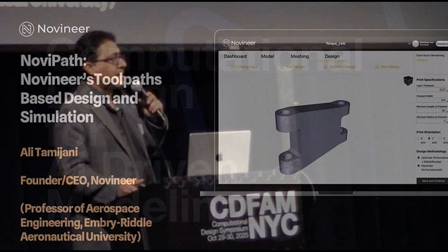So this is a short demo of how it works. You take a picture, provide that picture, and it creates STL and STP. Then you can go to the next module, apply loads and boundary conditions, and it optimizes the geometry. Then you go to the next module, provide material properties, and it optimizes the manufacturing toolpath. Here are some additional examples, for example NaviVision, where you can see you get both STL and STP.